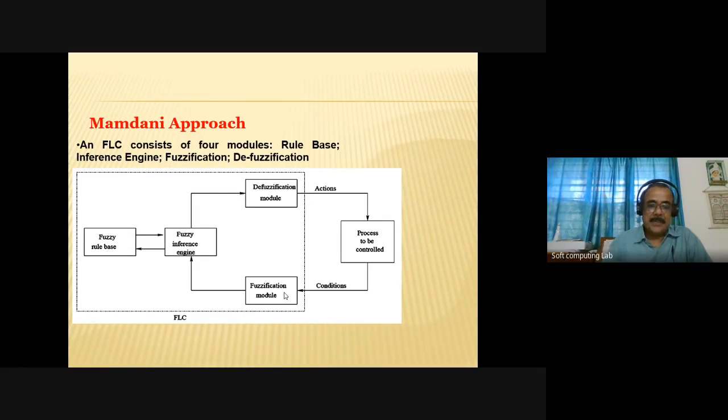Okay, now supposing that I have got 5 input variables. Out of these 5 input variables, one is temperature, and I have got this particular membership function distribution. The moment I pass the temperature, might be 12 degrees centigrade or whatever, corresponding to this 12, if I just draw one vertical line parallel to y, what will happen? It is going to intersect the very high triangle and the high triangle. Can you see that? So it is going to intersect both high as well as very high temperature triangle.